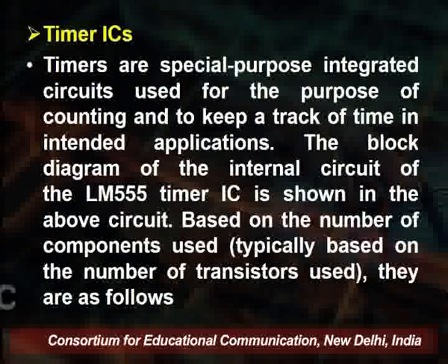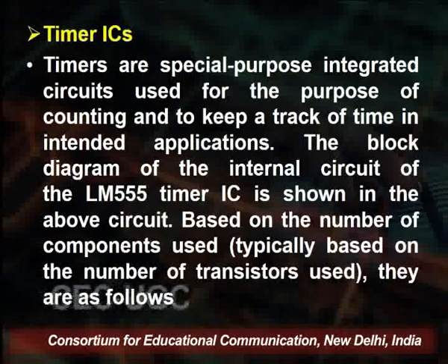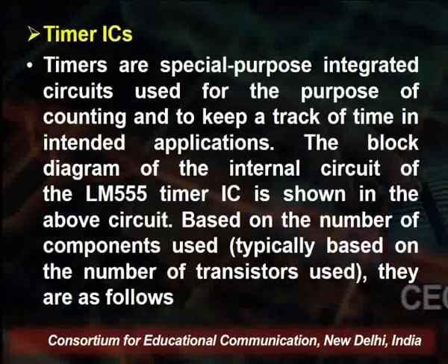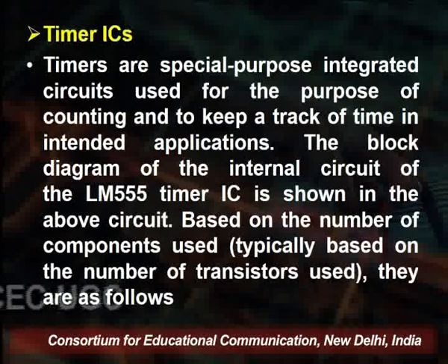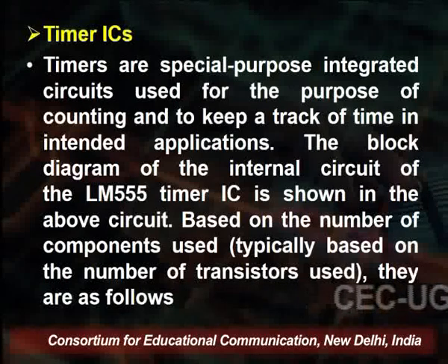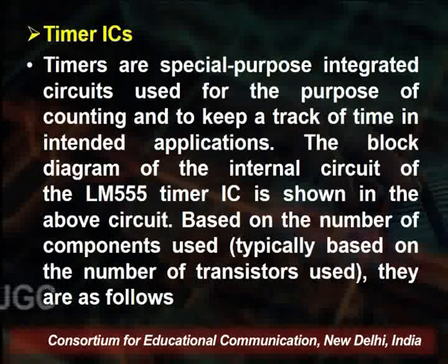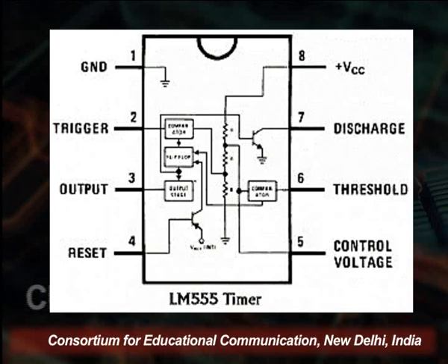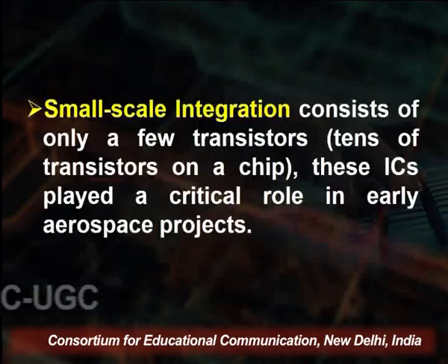Next are the timer ICs. Timers are special purpose integrated circuits used for counting and keeping track of time in an intended application. That integrated circuit is the LM555, which is called the LM555 timer IC. It is classified based on the number of components, typically the number of transistors used, as follows. This is the LM555 timer, which has ground, trigger, discharge, output, threshold, reset, and control voltage. All the parts are here. It has a function.